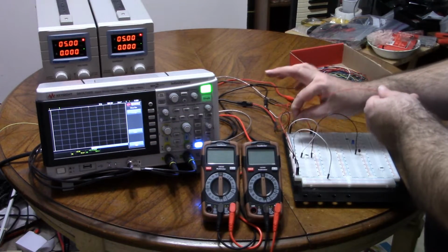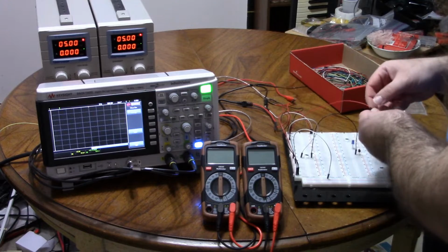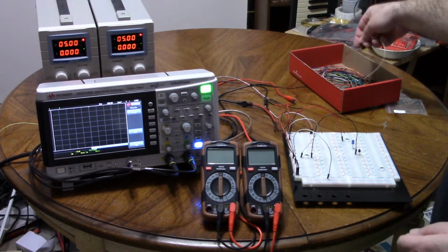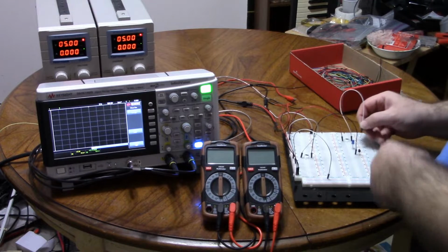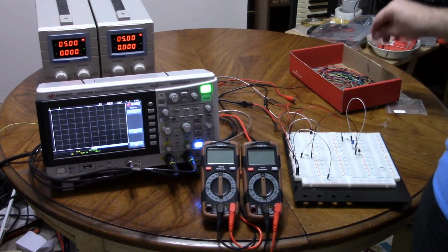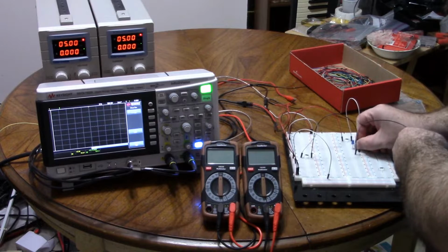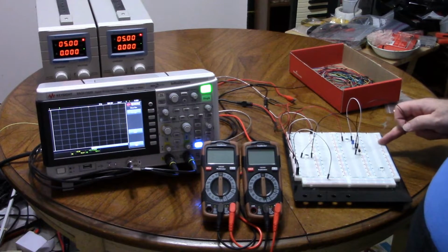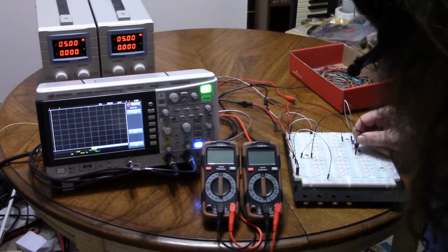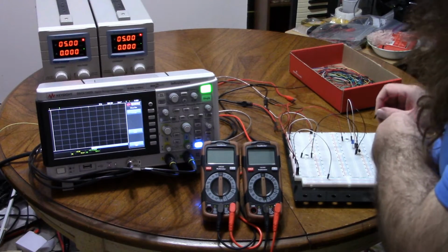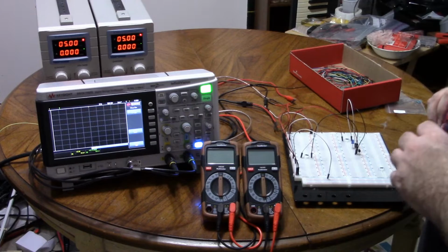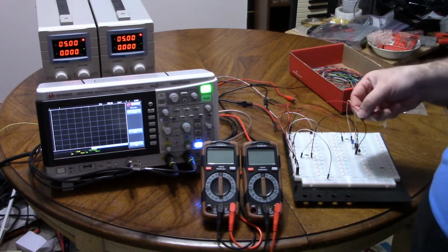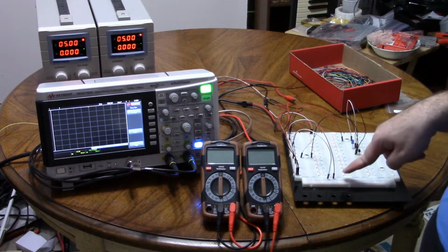I'm going to take the positive of the positive power supply through a 10k resistor to act as the collector resistor, out of that resistor through an LED just so we can see what's going on. This is essentially the output and the load. The LED is in series of where you would take the output. So we'll connect that to the collector, and I'll connect the emitter. Actually, I'll leave the emitter alone for a moment. So I'll connect the negative of the positive power supply into my little shared ground spot.